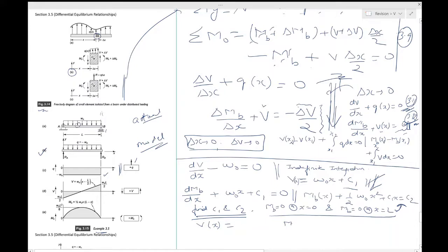Okay, so you will find out that this is true, and once you have these two things, you can draw the shear force and bending moment diagram. Okay, one of the important things which you should note right away is that, unlike the previous cases, you did not actually ever find what RA and RB were. Okay, so that's where this is a unique method.